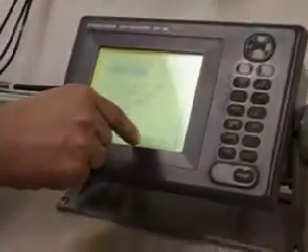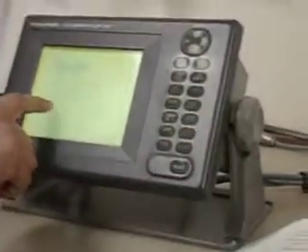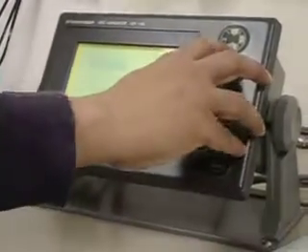is now system setting. Under system setting, again there are 9 submenus: plotter setup, unit setup, data output setup, data 2 output setup, data 4 setup, GPS setup, DGPS setup, line of position setup, clear the memory. So from here it is GPS setup. Choose number 6. First number 9, then number 6. So now I choose like this. Highlight number 6, GPS setup, press enter, this button. It is the main place where you set up the GPS.